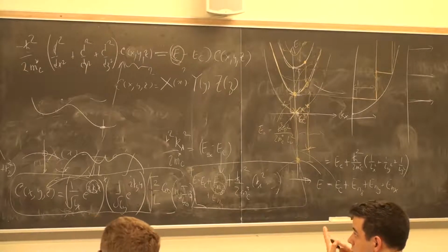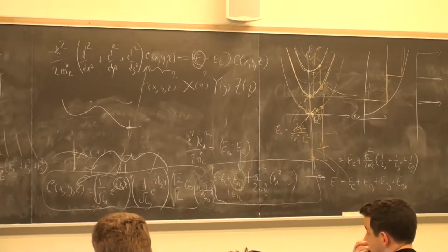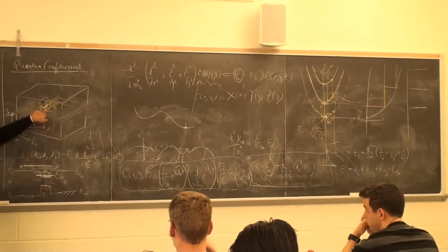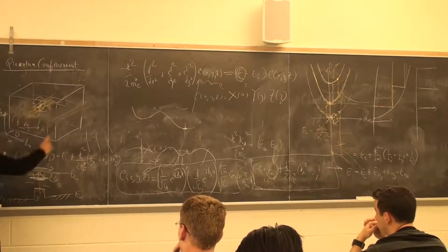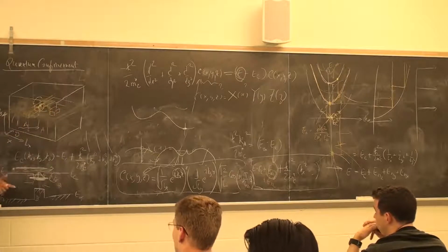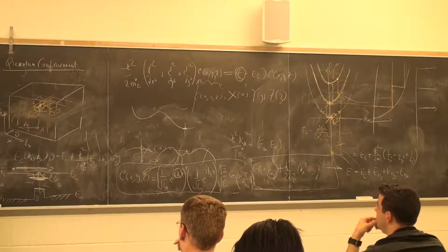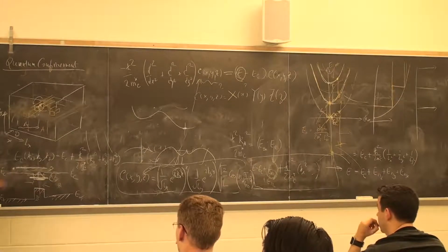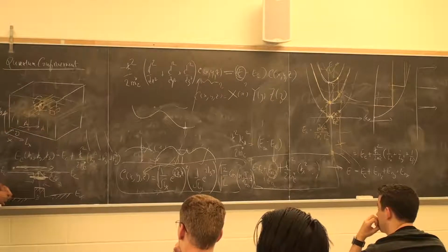Absolutely. So you're saying that if I integrate the density of states, the total number is very low. If I have only one dot, it's extremely low, like 1 compared to 10 to the power 23. Absolutely right. So whenever we use quantum dots, we have a huge number of them in parallel. So the total density of states really depends on the total number of these quantum dots too. Okay.